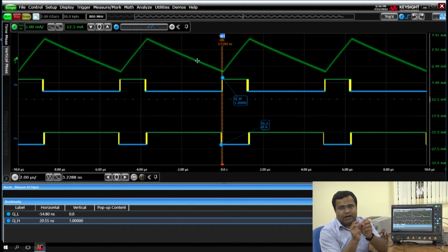So if you provide a fixed dead time, which is a conservative choice, then under light load or low current conditions you are unnecessarily turning on the diode and it can get into a more lossy condition. That's why you may have to adaptively vary the dead time. As the load current increases, you have to increase the dead time. As load current decreases, you have to decrease the dead time. In this way, you can minimize the losses due to the diode reverse recovery. You can try to minimize that effect by means of adaptation, and this is one of the reasons that people go for digital control.